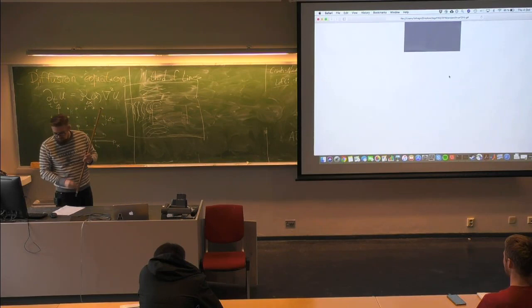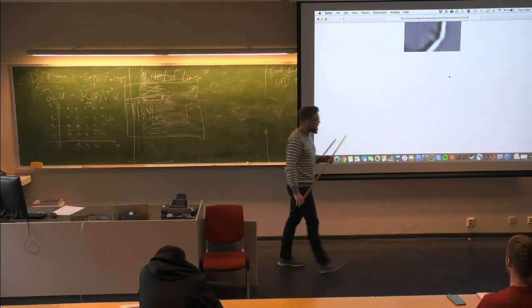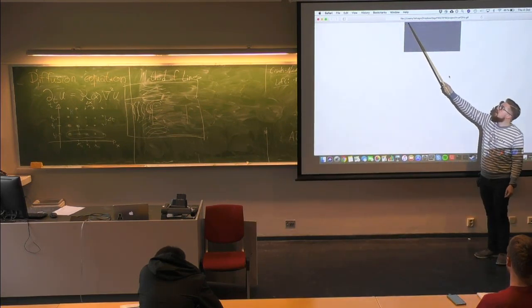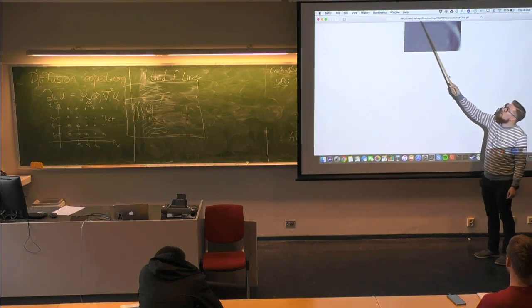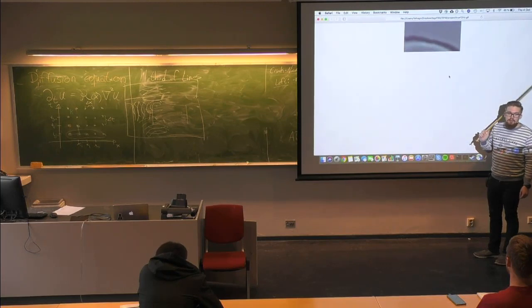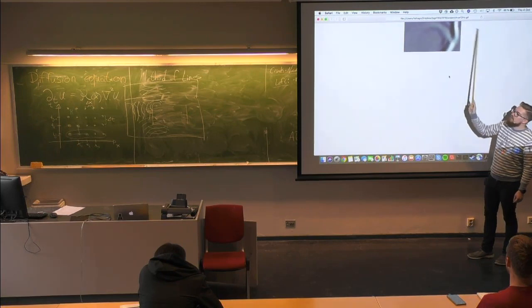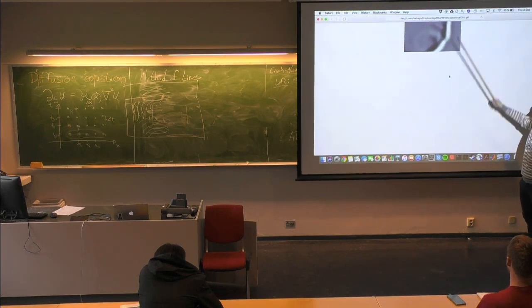Why is that? Well, what I'm actually doing here is running multiple simulations. I'm running one shot from this grid point, then the next grid point, and now you see it's all the way over there. So I'm collecting data from all of the different shots. And I'm also recording the response at the top of this box. As long as the false reflections do not reach back to the receivers, they don't really exist. You don't measure them, so they don't matter.